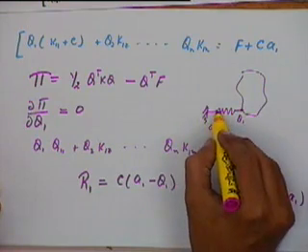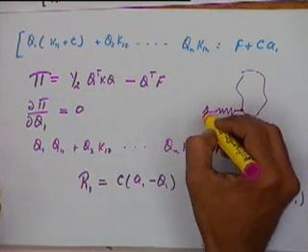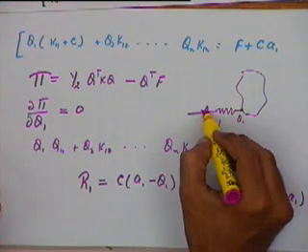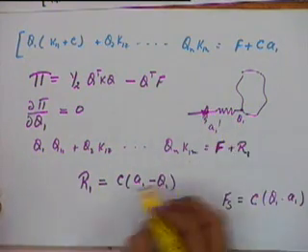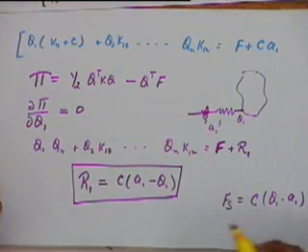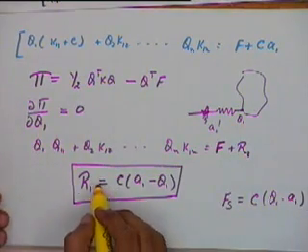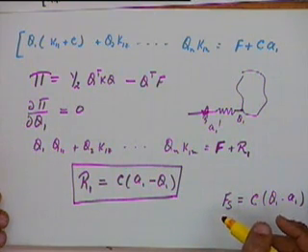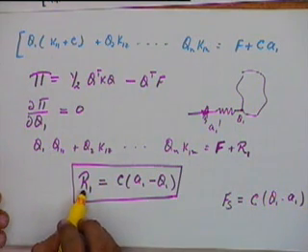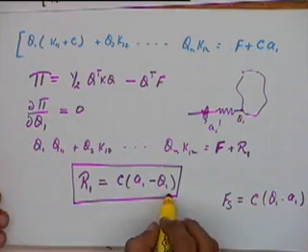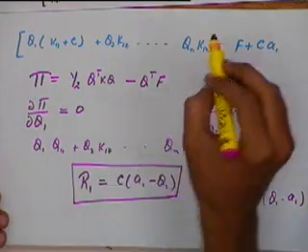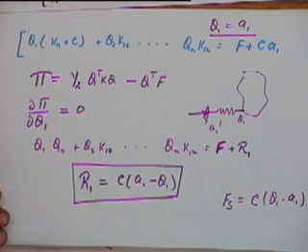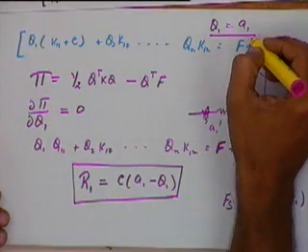Okay, the force of the spring will be equal to the reaction in magnitude. If you consider this node at this point, whatever reaction you are having from here will be equal to the force in the spring, which is exactly what this relationship is telling us. Or if you just consider the magnitude, you can say C times Q1 minus A1. So the reaction would be C times Q1 minus A1, that is for single point boundary conditions of the type Q1 is equal to A1, and when we are using the penalty approach.